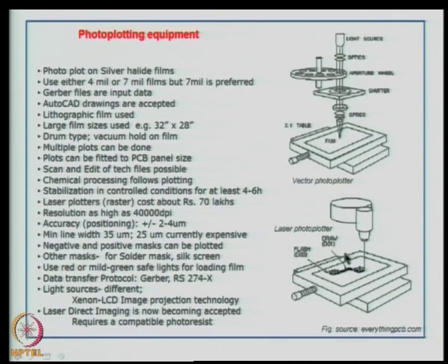Whereas, in a laser vector photo plotter, as you can see here, here also there is a light source. Okay. Now, basically because of the raster format, you will see irrespective of the D codes, they move very fast and the apertures are open very fast enough, and basically you are not looking at sequential operation, you are looking at the complete film, and the laser photo plotter and the laser source is so sharp that you can do this entire operation much faster than the vector. Of course, the light source used here earlier was different compared to the light source that we are using nowadays.